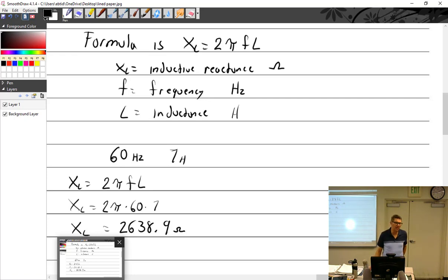All right, that's about all I got to say about inductors. Speak now or forever hold your peace. Everybody understands inductors. So here's some big takeaways about inductors. I think I kind of beat it to death. They take time to build up, take time to collapse. The inductance is based upon its properties, how many turns you have, what the core is made out of. Certainly the effect on the circuit is going to be based upon how the coil is made, how many henries it is, and what the frequency is.